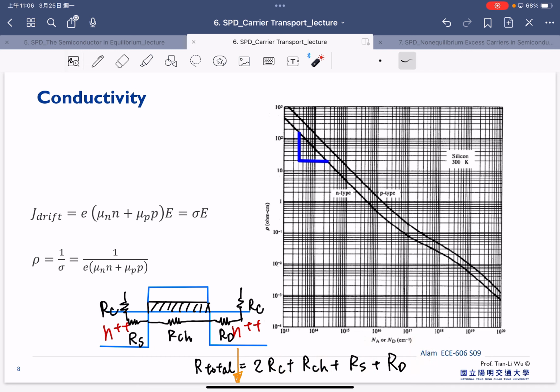For example, we have to optimize the contact resistance. If you start working on fabrication and measurement of your own device, you will realize why the RC is very important. The RC is directly linked to the current. If you have a low RC, you have a very high current. That's the purpose. So for sure, if we can reduce RC, that would be perfect.